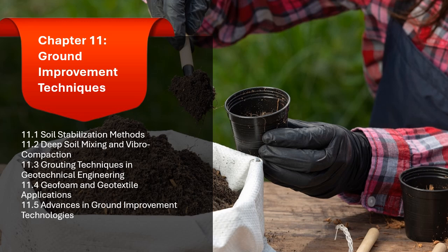The vibraflot is raised in stages while continuing to vibrate the soil, allowing for incremental densification at different levels. In some cases, the process is combined with the injection of water, air, or grout to further improve the soil's characteristics. 4. Completion.